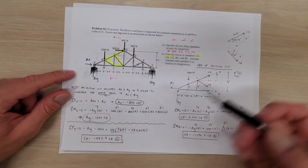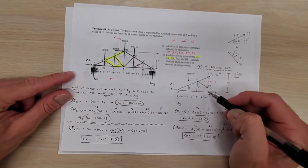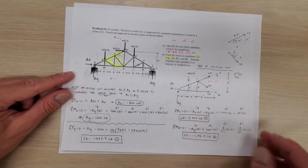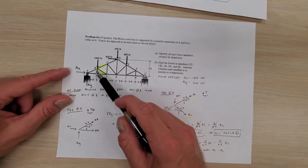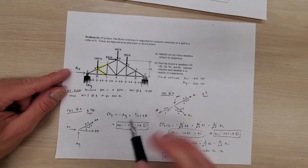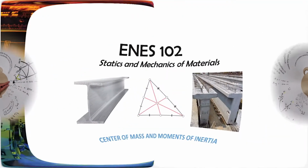Then after that we pretty much just did a method of sections, did some moment equations about the point where members intersect, both K and C, then did a sum of the forces in the y direction, and then pretty much using our knowledge of zero force members, figured out a pretty efficient strategy to solve using method of joints for the last two members that we needed to solve for. And there you have it. That's it.